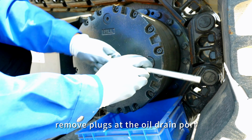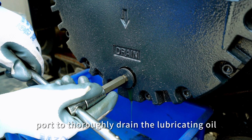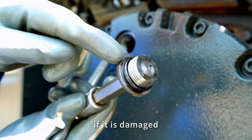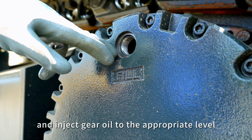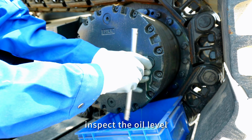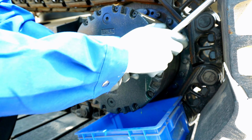Remove plugs at the oil drain port and oil level detection port to thoroughly drain the lubricating oil. Inspect the O-ring on the plug. If it is damaged, replace it in time. Install the oil drain plug at the oil drain port and inject gear oil to the appropriate level from the oil injection port. Inspect the oil level. Install the plug at the oil level detection port.